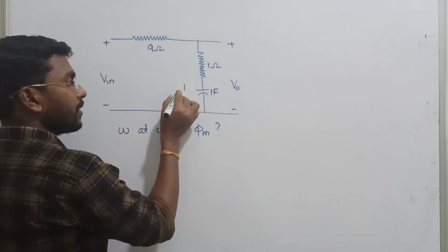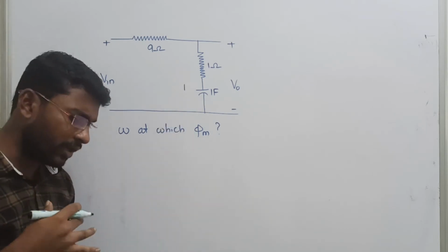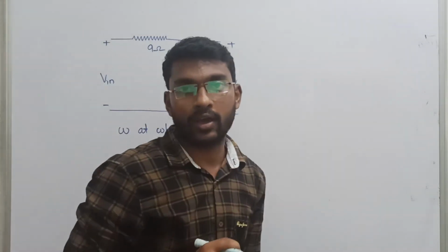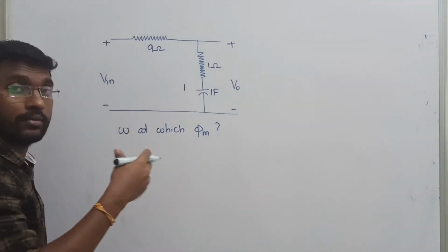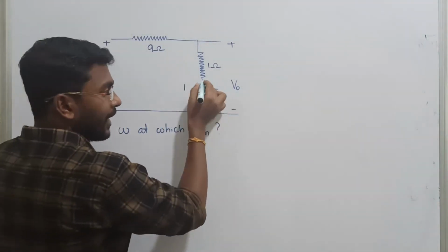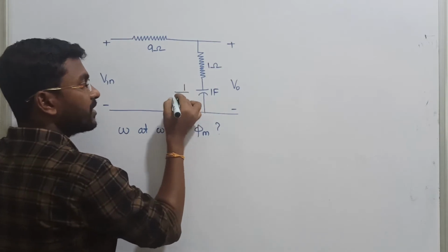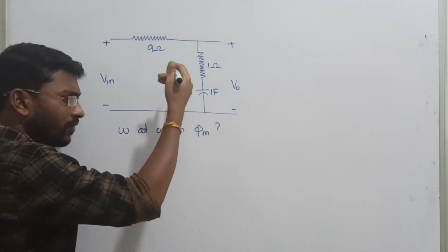So that capacitor, we are proceeding with the Laplace only, no? We are in control system. So the simplest way of bringing the transfer function is Laplace only. For that, we are converting all these terms into the Laplace domain. The capacitor in Laplace is going to be 1 by Cs. I am writing it in a general manner and then we will reduce it, right?